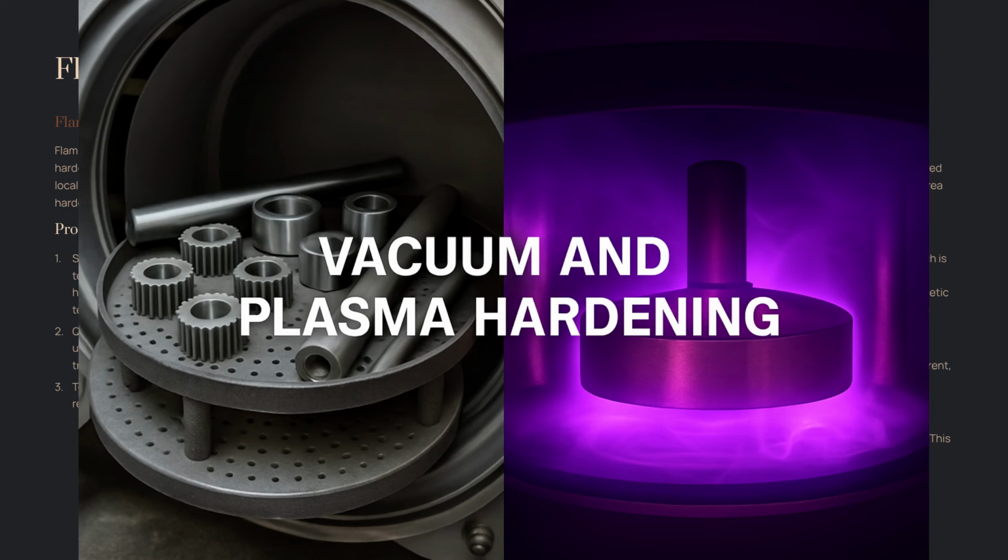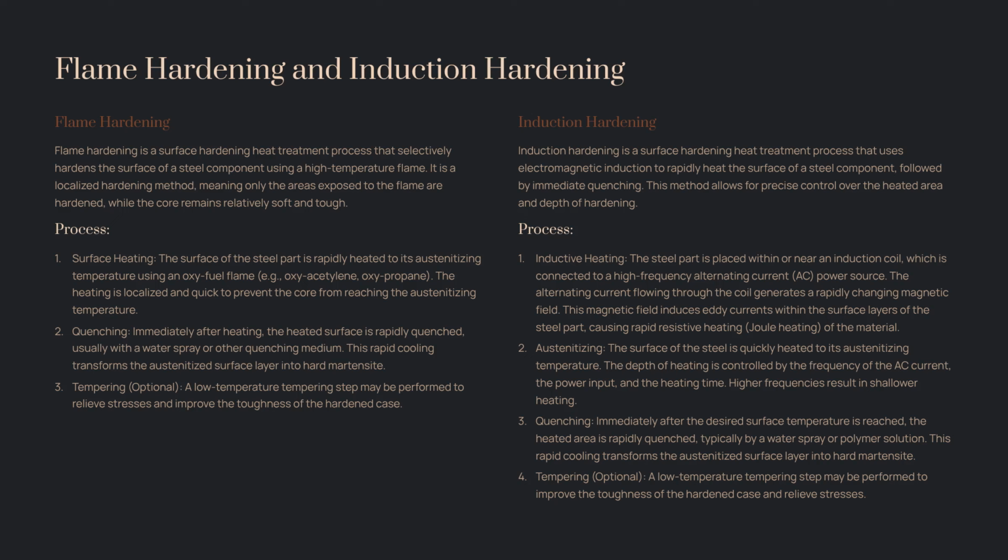Clean process. It is a clean and environmentally friendly process, as it does not involve open flames or chemical baths. Energy efficient. High energy efficiency due to direct heating of the workpiece. Applications. Induction hardening is widely used for components requiring high surface hardness and wear resistance, such as gears, crankshafts, camshafts, axles, bearing races, and other automotive and machinery parts.